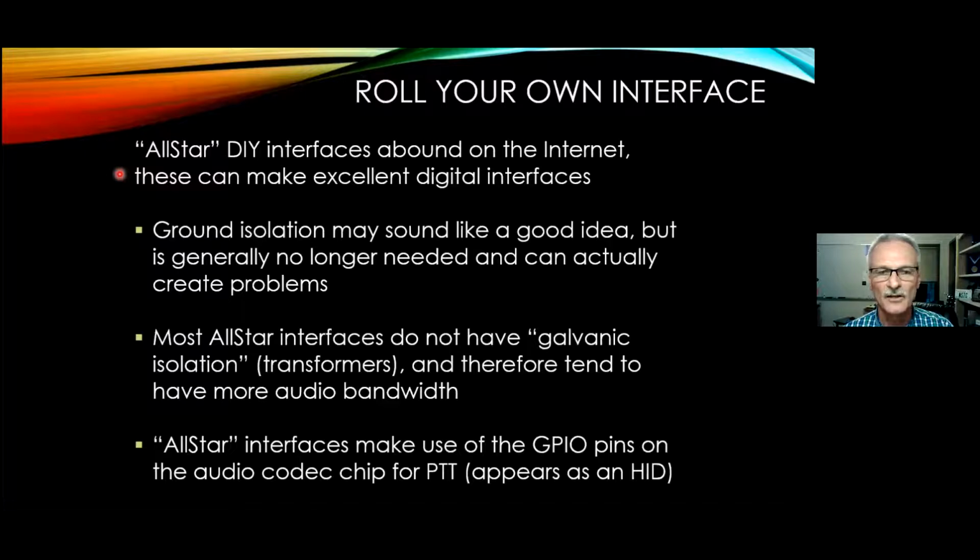And there's a lot of different interfaces out there to build your own AllStar repeater or your own AllStar simplex link. And why not start with a design like that that's already in use by a lot of different folks. Now, AllStar is, of course, a voice application, but these seem to work just fine for digital operations. We might limit the audio bandwidth a little bit for voice applications, but the interface can certainly handle much more bandwidth than what we're using for voice, and it works perfectly for digital.